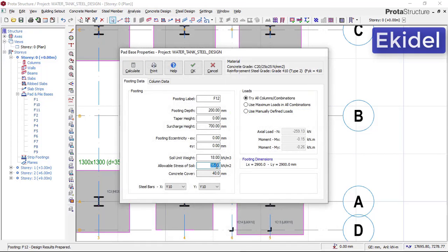The reason why this happened is because I changed the bearing capacity. So the program is seeing that this bearing capacity of 35 is very low, which means that pad foundation is not recommended to be used for this kind of bearing capacity. So what is okay to use for a bearing capacity below 50 kilonewton per meter square is either a raft foundation or a pile foundation.